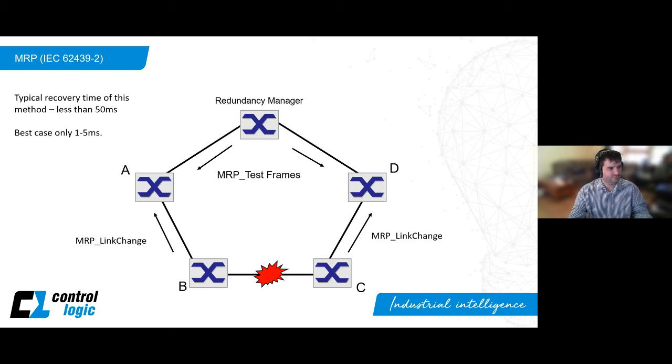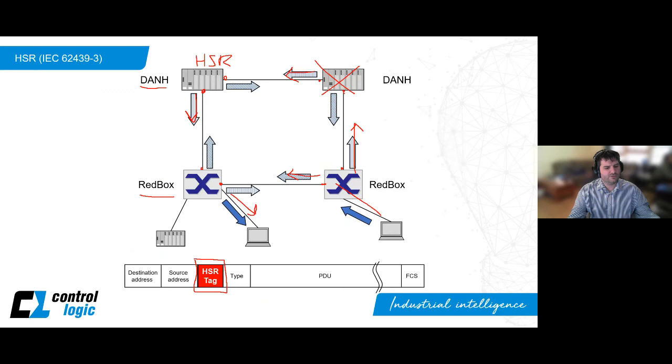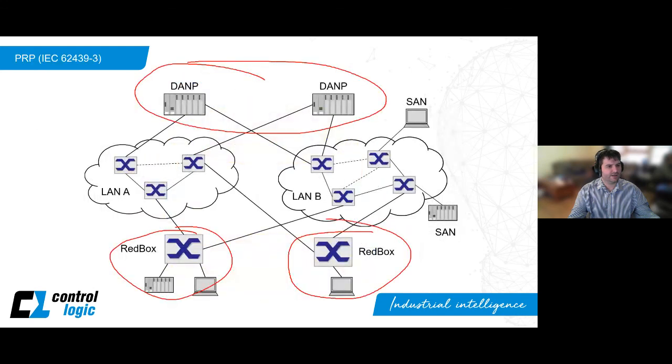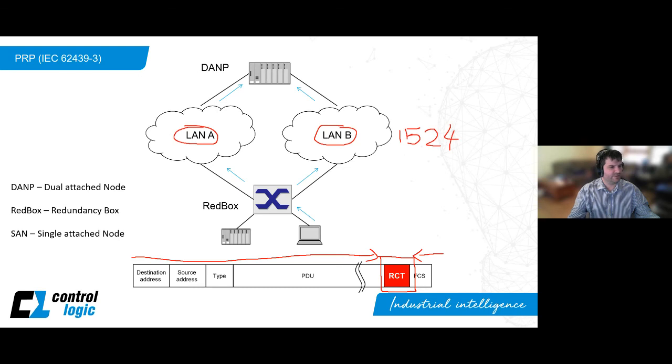Excellent. Thanks, Adam. Michael had another question as well with regards to infrastructure that already has redundant VLANs for each PLC and SCADA connection. So where does PRP benefit over an existing solution? I assume based on what Michael's saying, he's talking about the PLCs having two network cards going to their own separate VLANs, maybe in separate hardware.